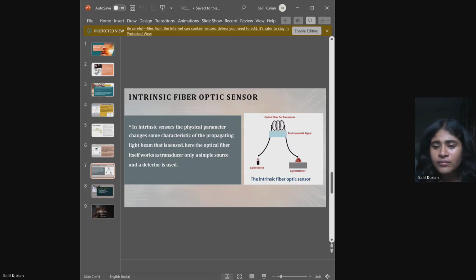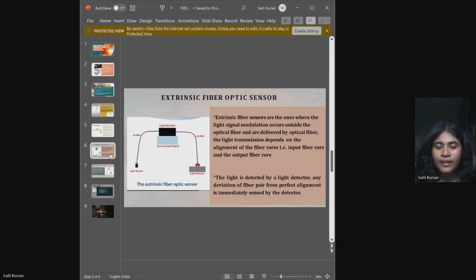So that is a Bragg grating sensor. It usually senses strain and temperature. So that's what an intrinsic fiber optic sensor does. Okay, so when we see a comparison between extrinsic and intrinsic, we will know the sensing principle. The extrinsic sensor is the sensor that I talked about, the oil well. That is a high temperature external transducer we use.